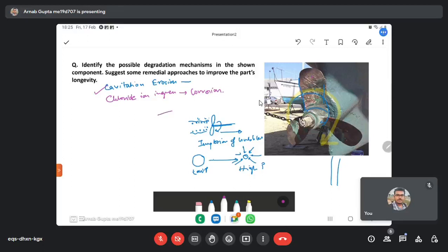this pitting corrosion is dangerous because at the surface you can see small pits, and that's it. But beneath the pits, generally there are possible regions of crack initiation and propagation. So that is not visible to us, and the material generally fails from beneath. So this part will come off if these two crack lines join. So this type of corrosion is something we don't want. So this pitting corrosion happens.